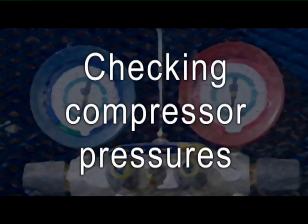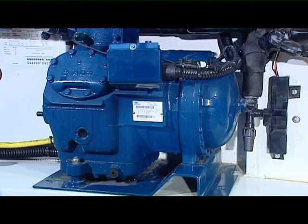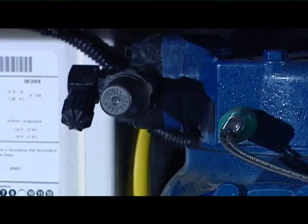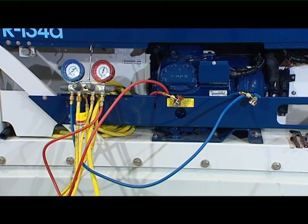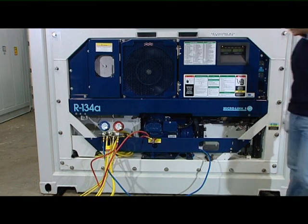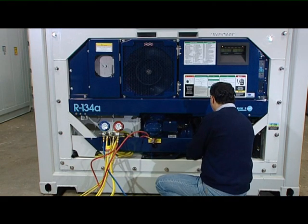Checking compressor pressures. A suction valve and a discharge service valve have been installed on the compressor. These valves allow the service technician to monitor system pressures and to perform service procedures by using the manifold gauge set. Without this tool, supplied to each vessel, it's impossible to know the system pressures and how the refrigeration system is operating.